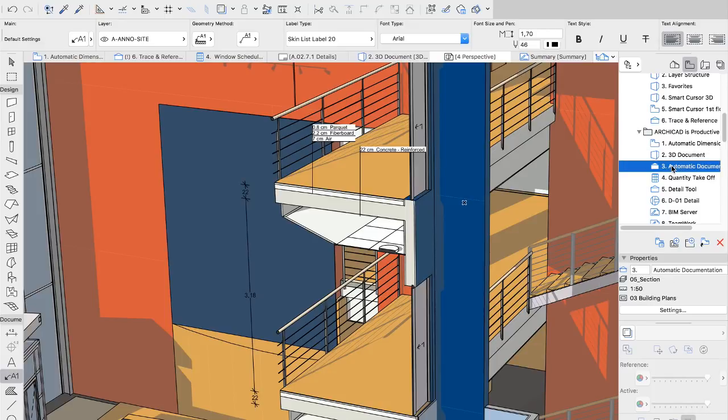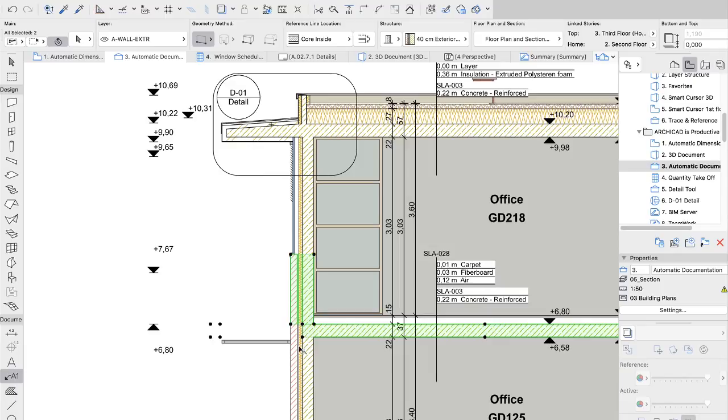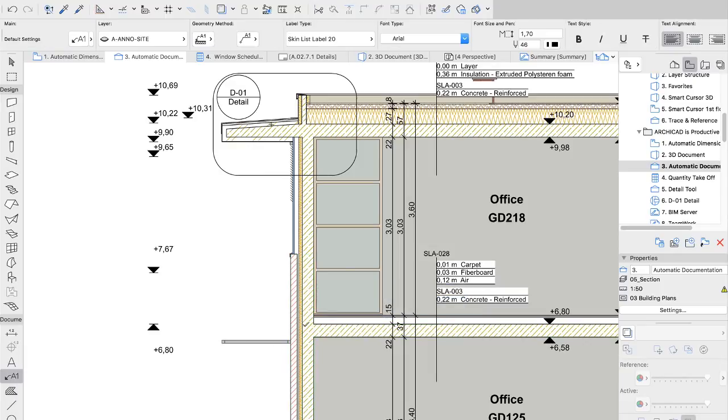Let's have a look at a section. This is a model view. No additional drafting work has been done to finalize this view. Yet the composite junctions look perfectly okay. All this is due to the smart building materials and intersection priorities. Your construction documentation can be automatically derived from the BIM without additional 2D drafting work.